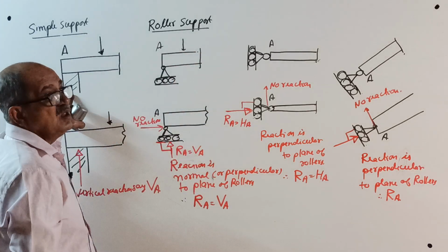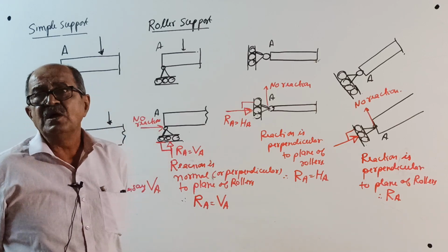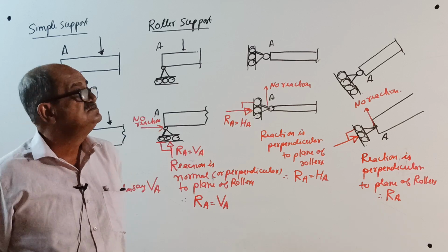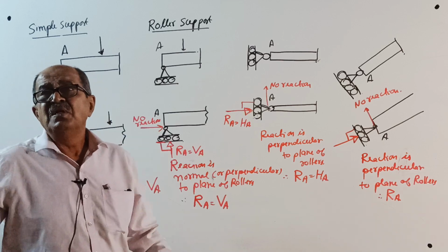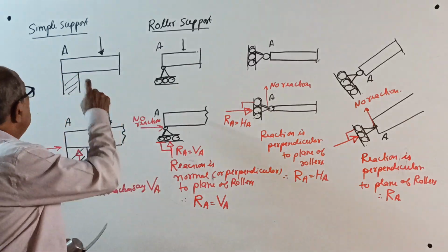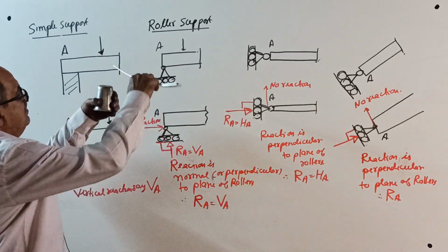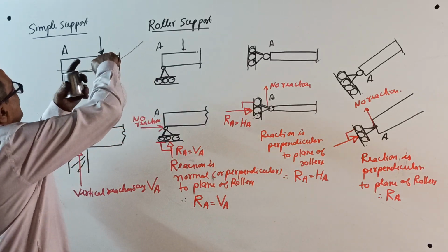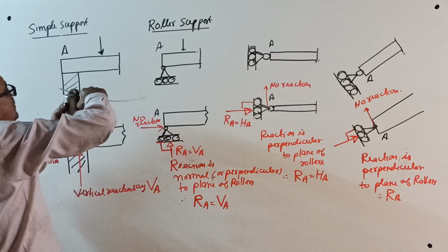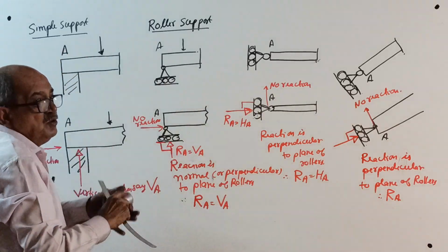This can be a wall. It can't be an RCC column, because then it becomes a rigid joint. It can be a steel column where a plate is provided and some member is resting. There is no connection between these two. It is not monolithic, like this. Now, if you apply a loading this way, it cannot move vertically. So, you should write here.